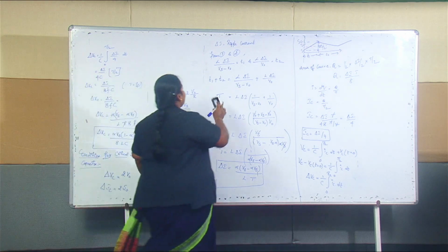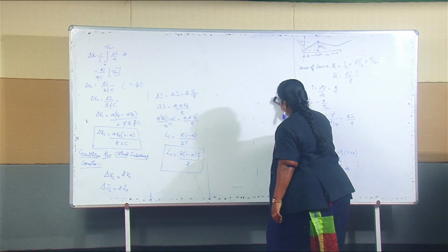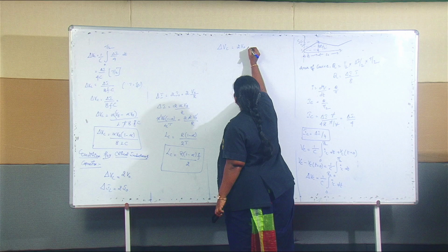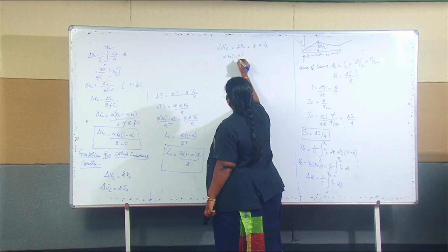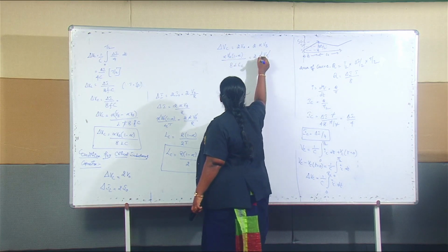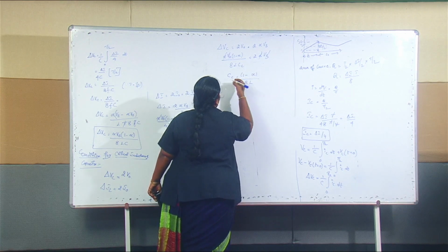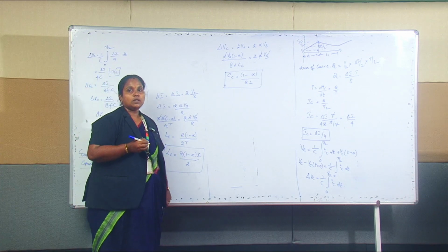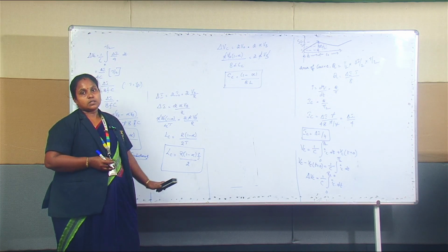Similarly, for capacitance, we have taken del Vc equal to 2 times V naught, which is equal to 2 times alpha Vs. So del Vc is alpha Vs (1 minus alpha) divided by 8 L Cc, equal to 2 times alpha Vs. The Vs and Vs, alpha and alpha will get cancelled. So Cc is equal to (1 minus alpha) by 8 L. This is the critical value of inductance and capacitance which has to be considered while designing your circuit. When we are using this kind of power supply for any application, this design value plays a major role, so these things have to be considered.